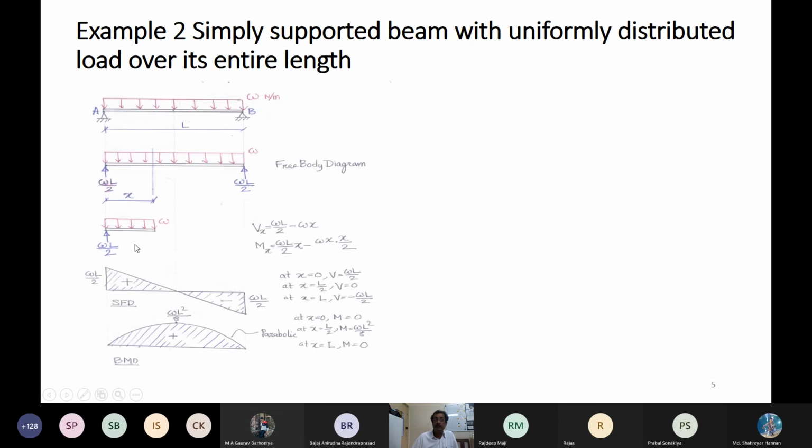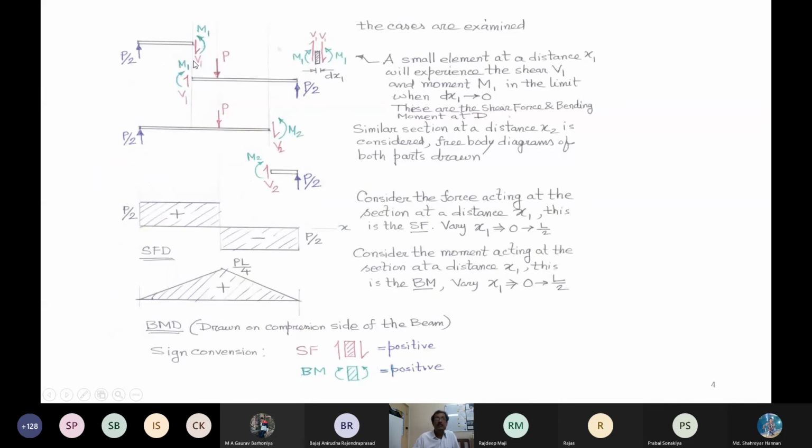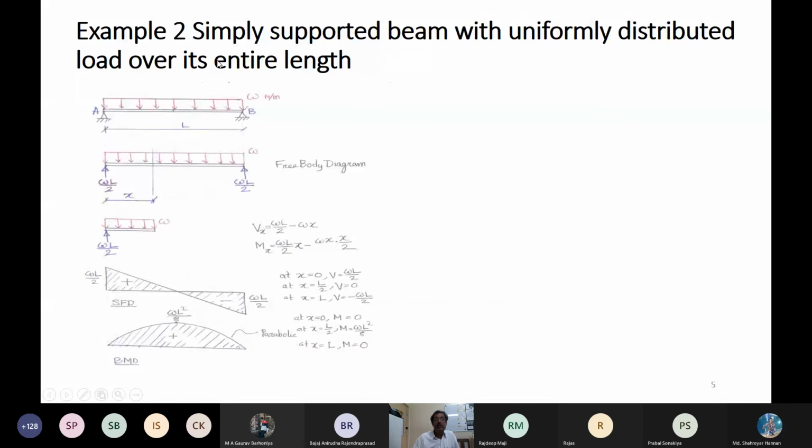That means you are correct. You are right. The shear here is vertically downward, and that is how we designate it as positive shear. It is the right part, I am looking towards my right, so right down is positive. Don't confuse. If there is any confusion, don't think. Designate it just as you agreed. If it comes positive, you are right. If it comes negative, you are wrong.